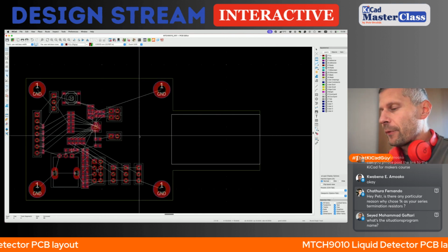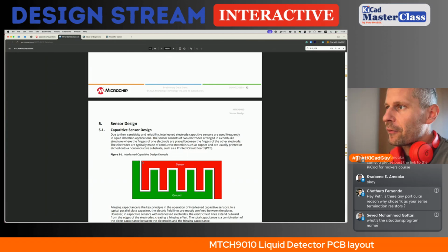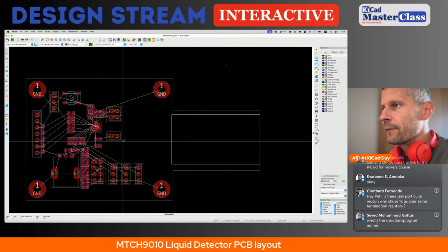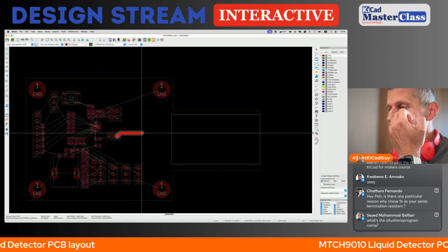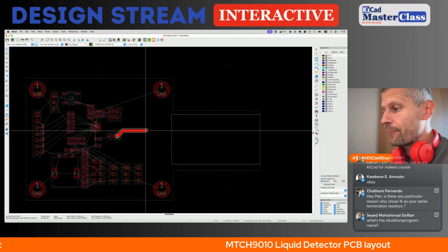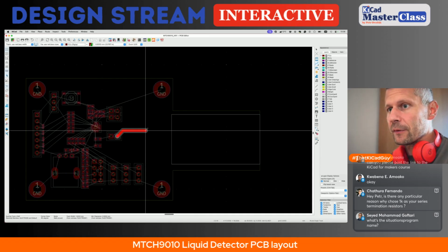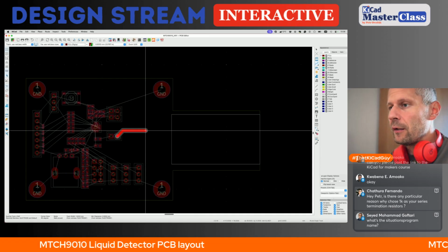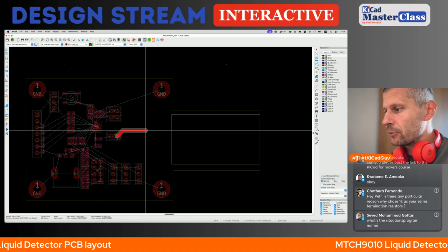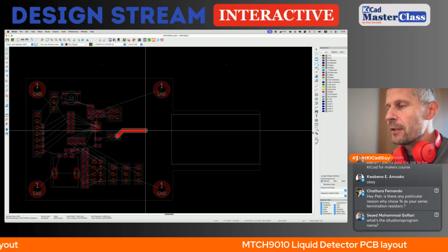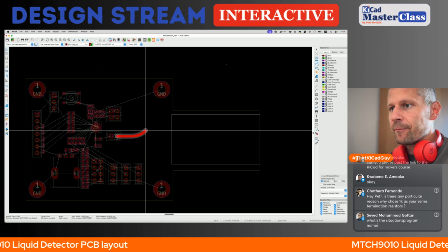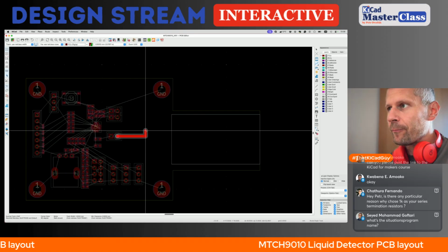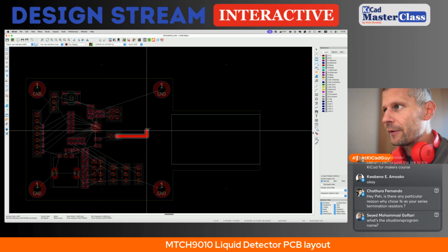You can see, let's get back to the datasheet. There are right corners. So the default setup for KiCad is 45 or 135 degrees, but we have some routing options. So when you press command and slash on Mac, and I think control and slash on the other platforms, we can change the rounding mode. This is the 45-degree rounded corner style. Here is the 90-degree corner style, and we will use this.